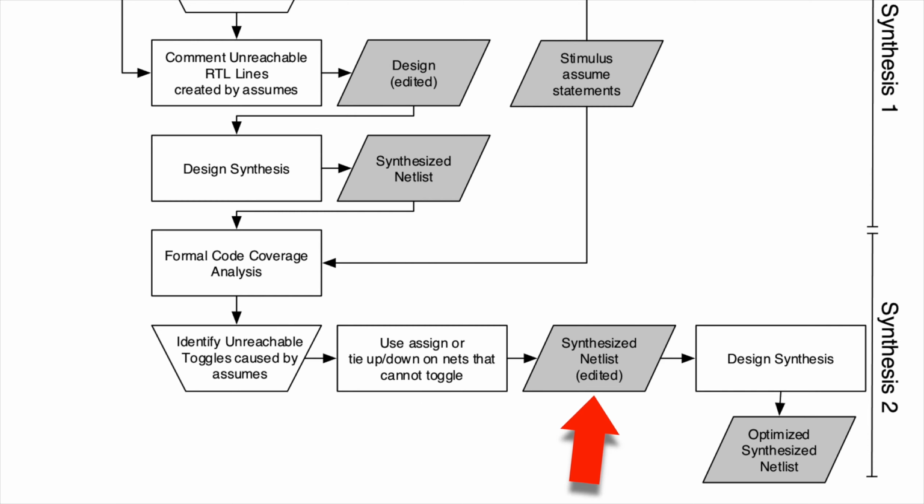Remember, synthesis is very smart about realizing that there's constants in the design, and tying a node up will allow synthesis to actually reduce logic safely and recursively as it goes through. And we will get another optimized synthesized netlist.